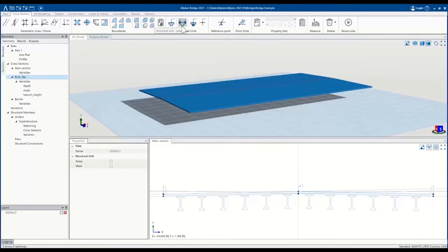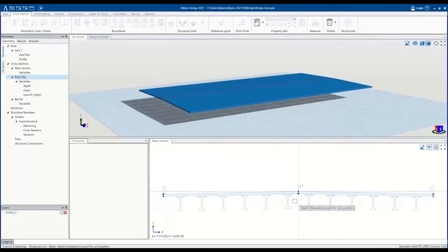And then just to refine and really define our cross section to make sure the reporting is well organized, we'll apply beam elements to these different segments. So we want all the girders to be part of one beam element. So we'll use this Boolean operation to combine these two boundaries to behave as a single category of elements.